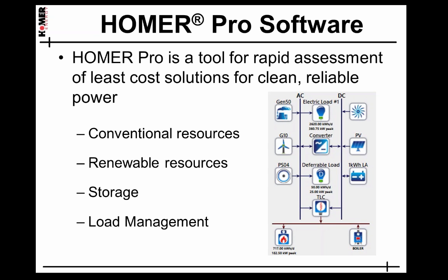It allows users to sort feasible systems by dozens of variables, and HOMER's optimization can consider interest rates, tariffs, sellback rates, emission goals, renewable resources, fuel prices, renewable goals, equipment prices, performances, and just a lot of options. The operational details of each possible system can be examined down to the minute or hour.